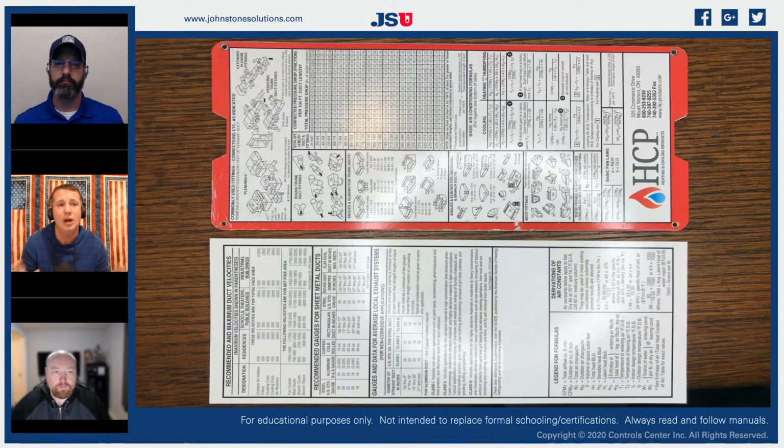So if you do not own a slide duct calculator, it's time to invest in one. They're very inexpensive, and some of your distributors will provide those for free, particularly if you're in a class. If you're taking one of my duct design CEU classes, you end up getting a duct calculator from Heating and Cooling Products. I buy a whole mess of them, and you end up with your own duct calculator because it's crucial. So many times we encounter ductwork issues in our industry, undersized ductwork. I mean, how many times have we gone on a job and we've had high static pressure, right?